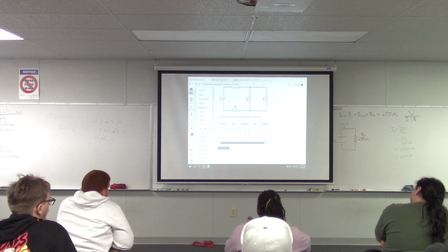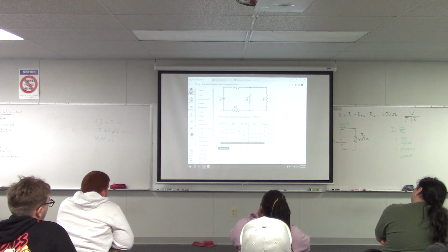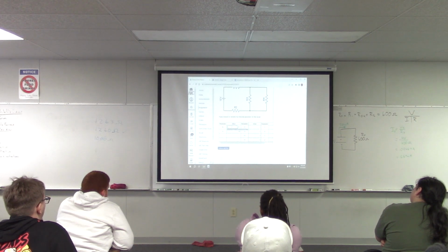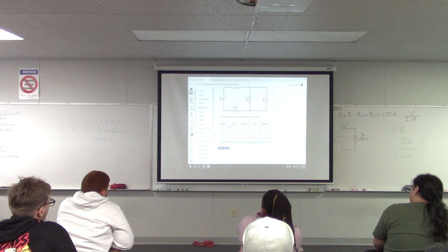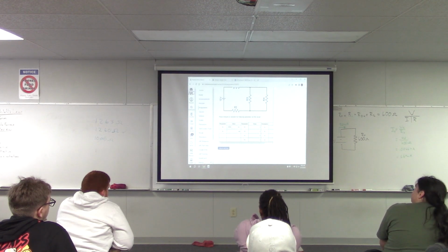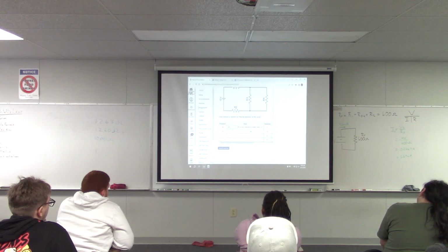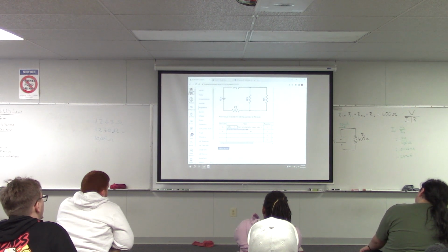So down here, the total resistance is in ohms. If I had, say, a total resistance of 10 kilo ohms, I would have to put down 10,000 ohms. I can't just put 10. I can't put 10K. It doesn't like abbreviations either. If you put 10K, it gives you this warning, it's not a decimal. So you need to actually put 10,000 because it's 10,000 ohms.